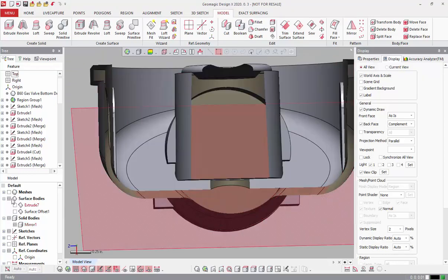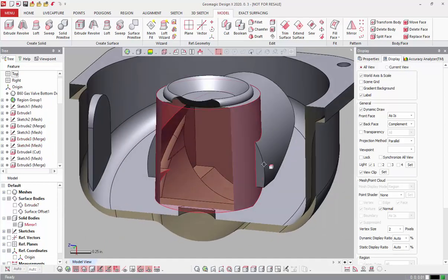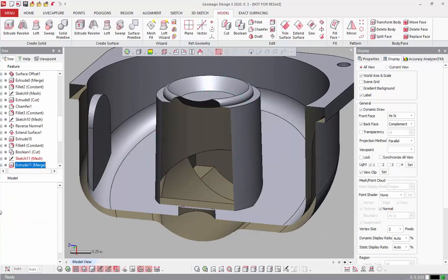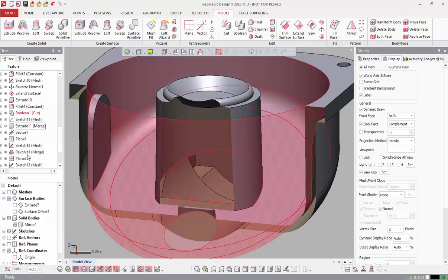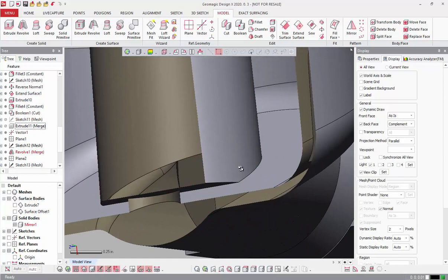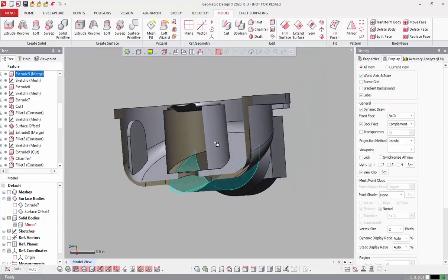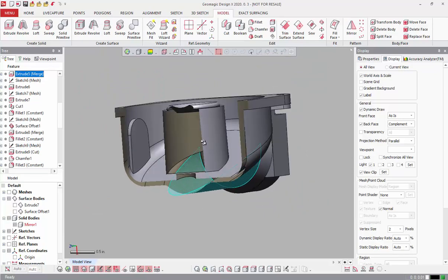So I want to make sure that this circle or cylinder goes all the way out. So what I'm actually going to do is, instead of editing this feature here, I'm just going to disable or suppress it in the feature tree. The reason for that is because I already know, I built this thing earlier, so we did a little bit of reshuffling beforehand as well.